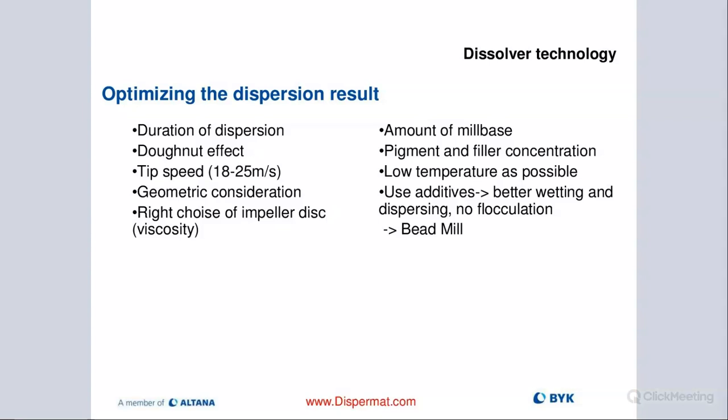Dispersing is an energy-intensive process. When we put in the power, the energy, we're running at high tip speed, we are automatically putting in energy. And that's what helps us break up these binding forces. But that also means we're going to have an increase in temperature. So when we are pre-dispersing, this usually isn't such a big problem. But when we're starting to mill, especially with the basket mill, we're going to put a lot more energy, and we definitely need to cool our basket.